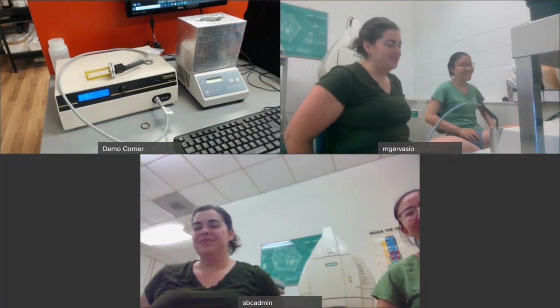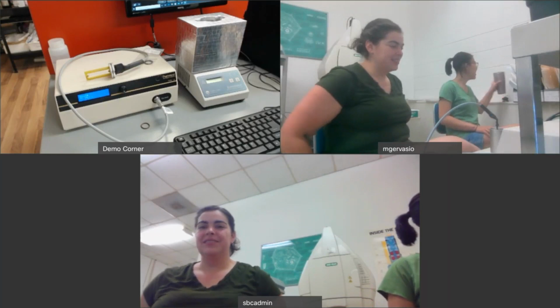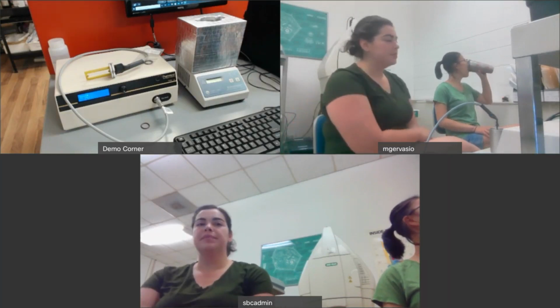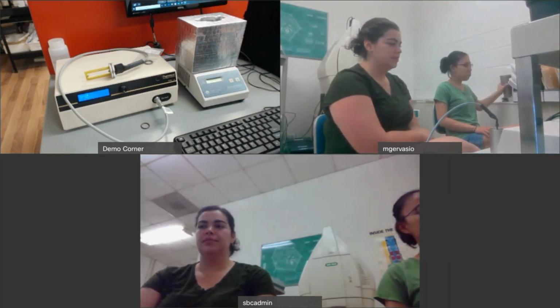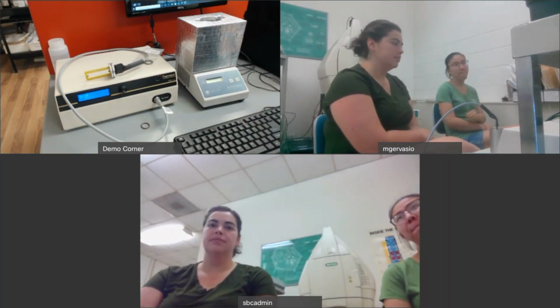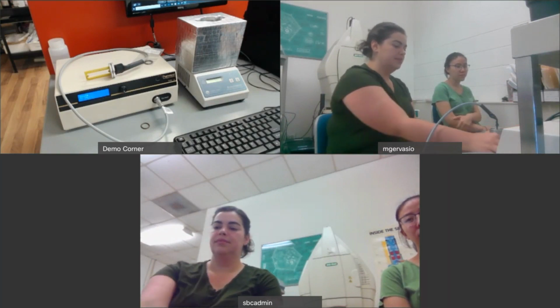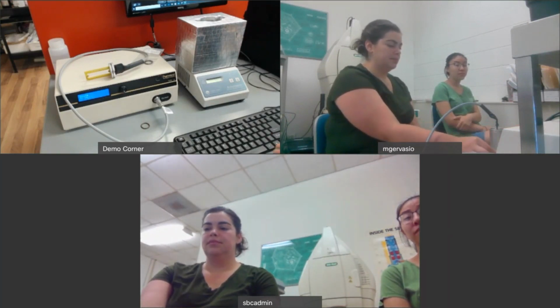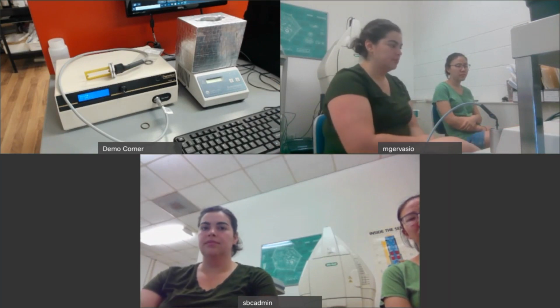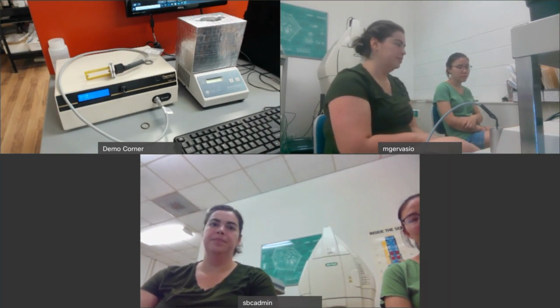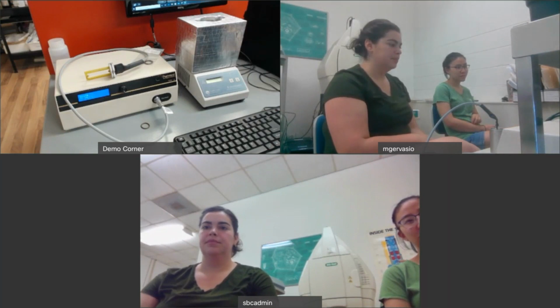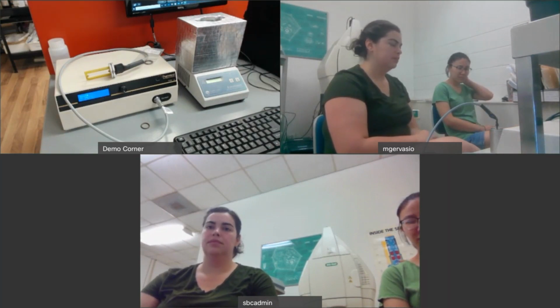The most important thing is, if you're trying to calibrate with a fluid that is not standard, or if you were trying to calibrate the sensor using a very high or, in your case, very low power, again, you will repeat the problem. That's why I said, now the power it's asking for is really high because of thermal conductivity. Let's try the standard, so it will be an average.